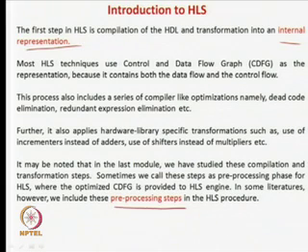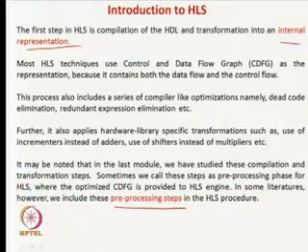Then we go for the pre-processing step. What do you mean by pre-processing step? We go for some kind of optimization so that the code is more optimized, does not have any redundancy, or uses better hardware elements like incrementers or shifters rather than adders, dividers, or multipliers. We keep the circuit very optimized, because we do not have any redundancies or dead codes, and finally we are using very good quality blocks. This type of optimization is called the pre-processing of the high level specification.